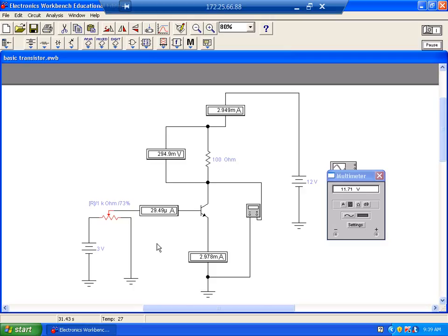That's the best I can do right there, 25 microamps. So 25 microamps, 31 microamps, 31.4 microamps. That means that guy's going to go up to 3.14 milliamps. I can do that in my head, right? You can just move the decimal point over twice. Then 3 point something milliamps dropped across the 100 ohms. What's that going to drop? About 300 millivolts, right? So my transistor should go up to about 11.7.